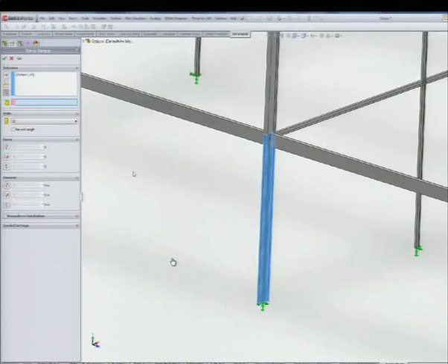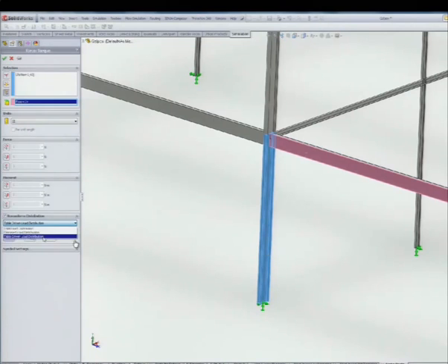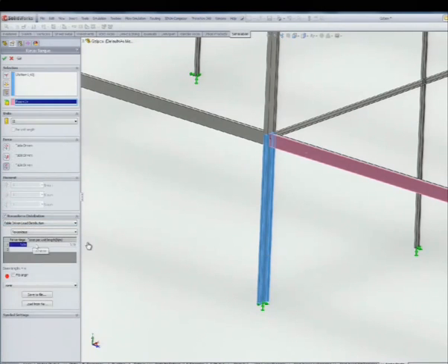And now I will set the non-uniform load. Yes, you see, these are the three options, as I told you: the triangular, the parabolic, and elliptical option. But in this case, I have to apply a random shape. In some way, a random shape is not triangular. So I will apply this shape, choosing table-driven load distribution. And these are the two columns, right? I have to fill this table.